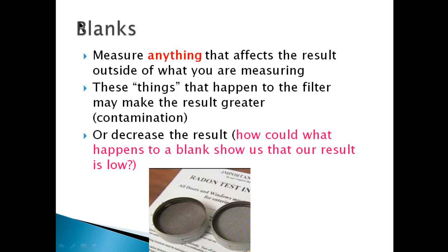Blanks. Okay, so what are blanks? So for people who are going to be using filters or any sort of device where you take it into the field, you expose it, and then it's analyzed at a laboratory, blanks are critical. Blanks are things that are just like your measurement method, but they don't make the measurement. You carry them with you wherever you go when you go out into the field, alongside the actual device